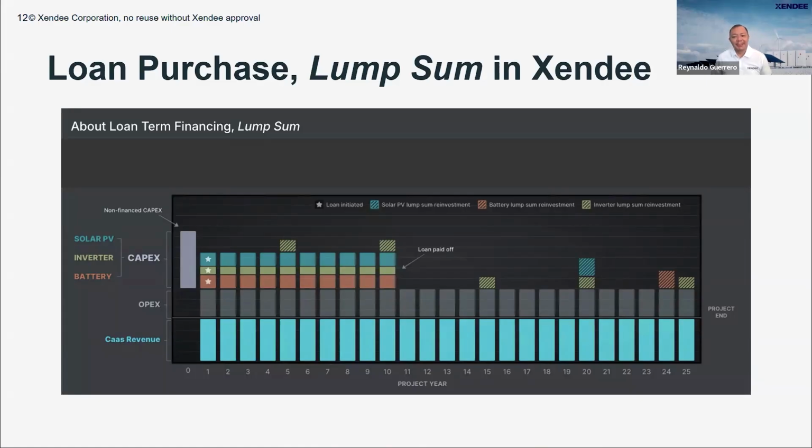For example, if there's a generator with a lifetime of 25 years, you're going to account for that huge replacement cost for that generator within the 30-year project. So it would disadvantage the generator because you're accounting for 2 generators compared to 1 for the PV. So again, it's possible that you could do that, but it may not be applicable in all projects.